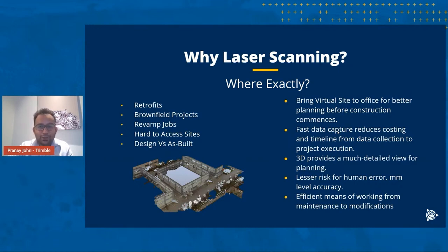So how will you do a survey if you cannot go to the other side of the valley? In that project, they used long range scanners to capture all the terrain information, get a terrain model in 3D, and then do their planning. So this laser scanning and surveying is what allows you to make that planning and allows your design to actually be built on the field.